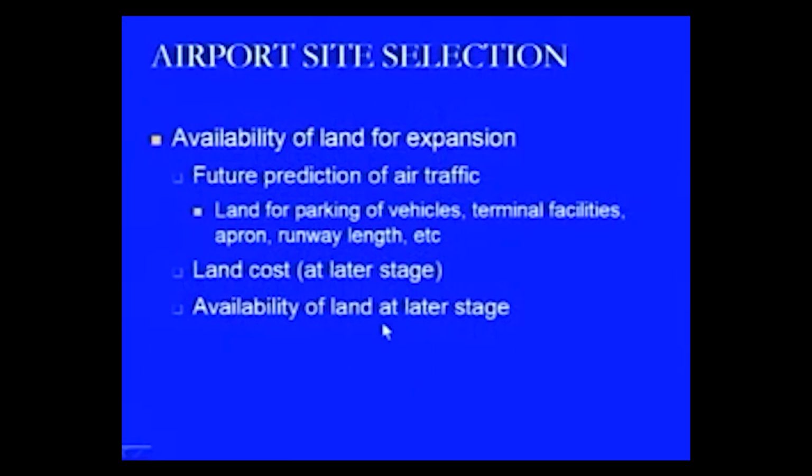Next is the availability of the land at the later stage, whether that is available at a later stage if it is not acquired in the initial condition, looking at the future expansion required. If it is not available, then we have to shift the whole of the airport, or we have to provide some additional space, and on that additional space the additional facilities have to be created. So, it is a more costly affair.